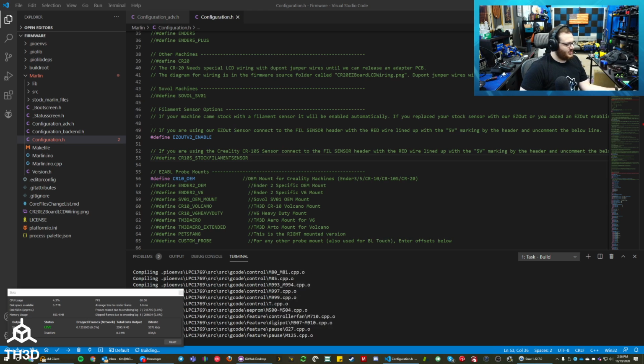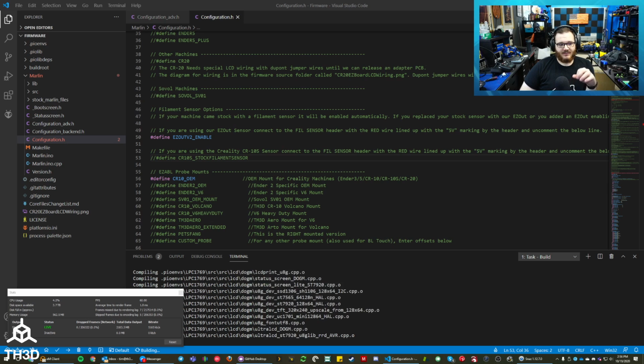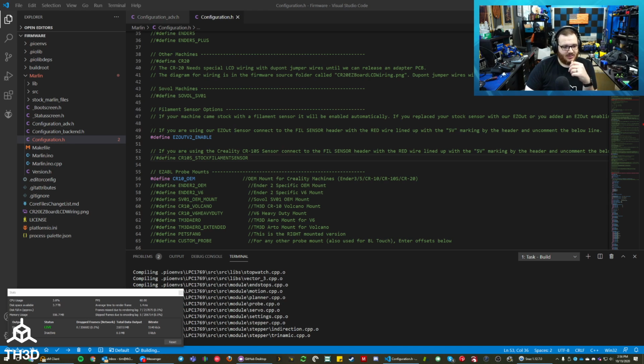Well, that compile, and I'll show you where to find the file, the firmware.bin file that you copy to the SD card for the easy board. Anyways, there are directions on the site. So if you go to uf2.th3dstudio.com, there's a download link for the easy board, and that's the firmware you want to grab. And there are directions on that page. If I show you here.